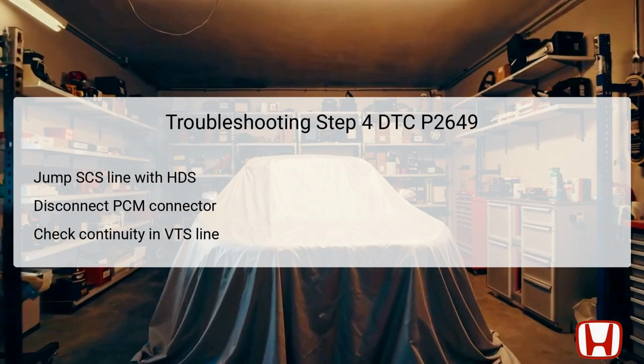If continuity is confirmed, it suggests that the VTS wire is functioning correctly, and further diagnostic checks or replacement of the PCM may be necessary. However, if no continuity is found, it indicates an open circuit in the VTS wire that requires repairs.